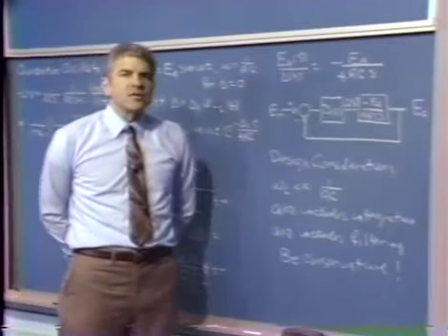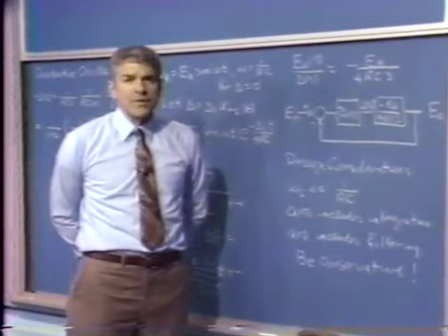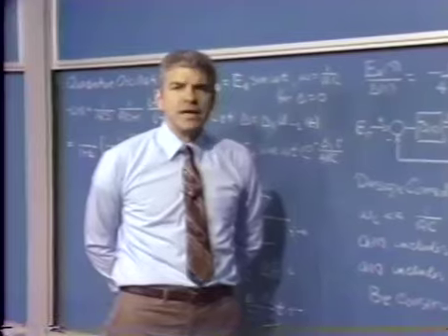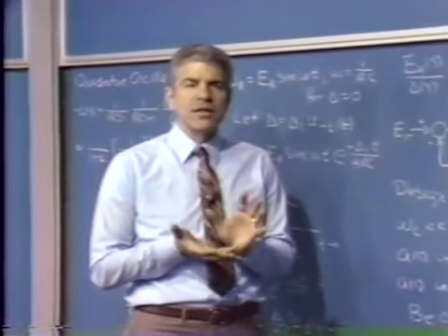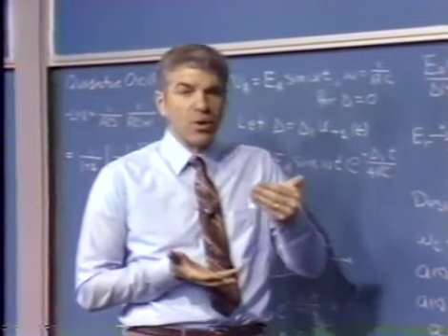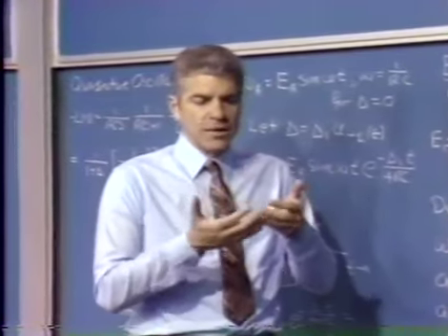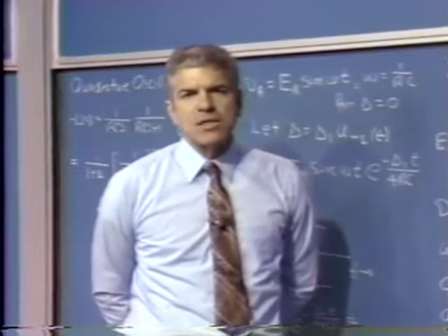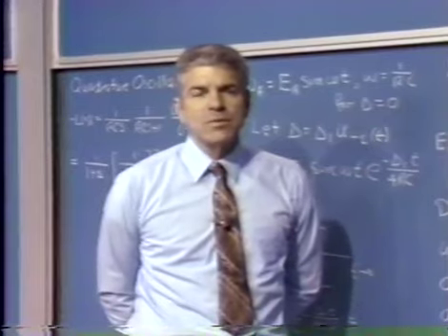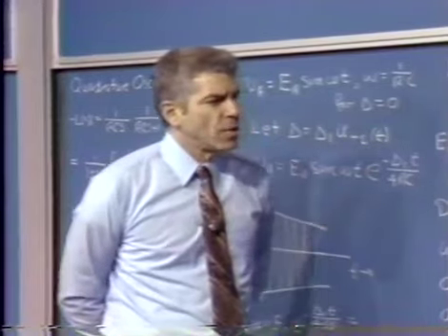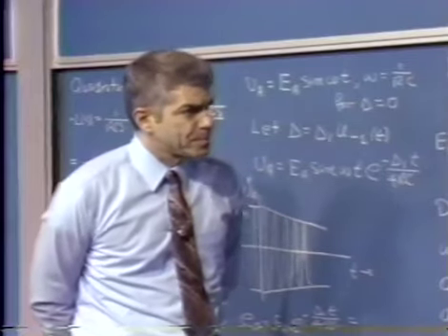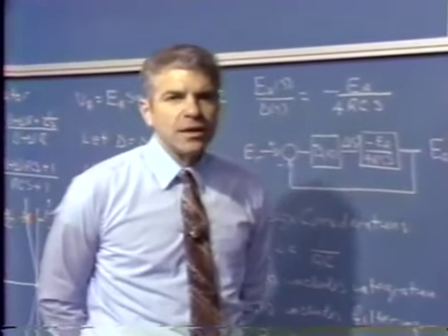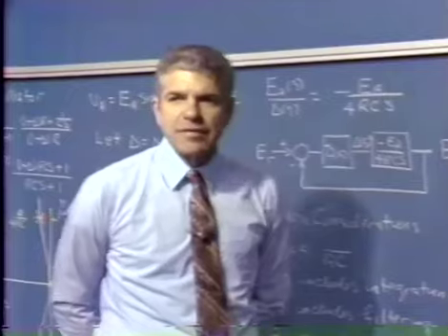There's a host of nonlinearities in this system. When you use a field effect transistor as a control element, and I do some of that analysis in the text, we find that it has rather grossly nonlinear characteristics between control voltage, gate voltage, and incremental resistance when we use it in this mode. So our system loop transmission magnitude at low frequencies may not be what we think it is. So we ought to design the system to be very, very conservative. Design a system that has plenty of phase margin under nominal conditions so that when things are not as we thought they were, we still have adequate phase margin.